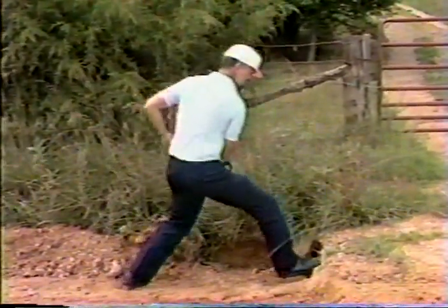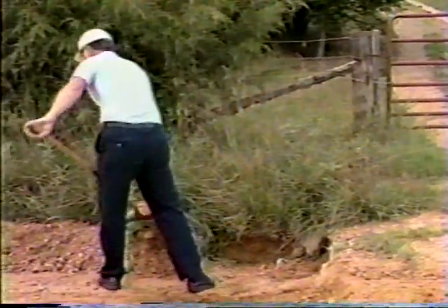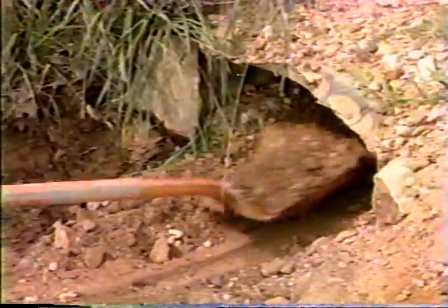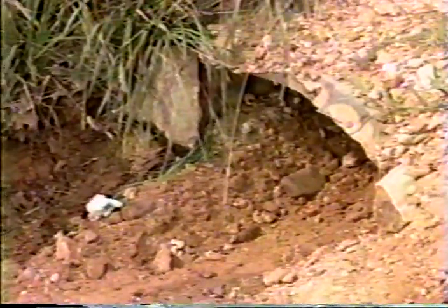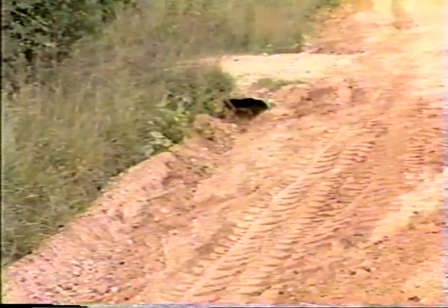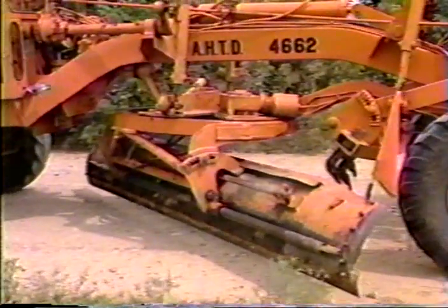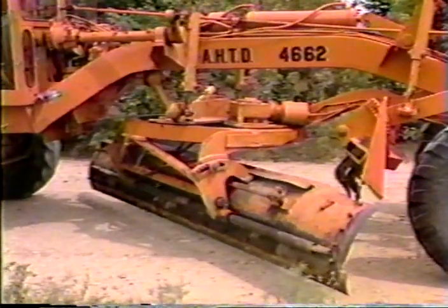If any excess material is present in the culverts or drainage pipes, it must be removed by hand. Improperly cleared culverts act as dams, allowing aggregate to build up and flooding of the roadway to occur. Drainage is the most important factor in maintaining a gravel road. Once the ditch has been cleared, the material must be windrowed into the center of the roadway.